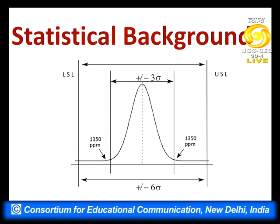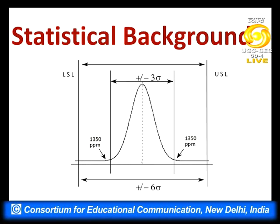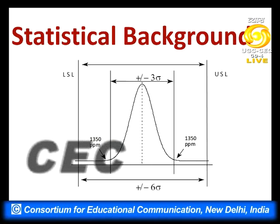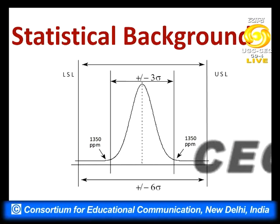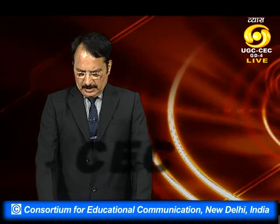As we have already discussed in the previous slide, the yield is 0.9973. If we subtract it from 1, it is 0.27 percent, which is nothing but 0.135 percent on both sides. These are the ranges where defects are there, and within these limits of plus minus 3 sigma, all the items which are produced are acceptable as far as the process is concerned.